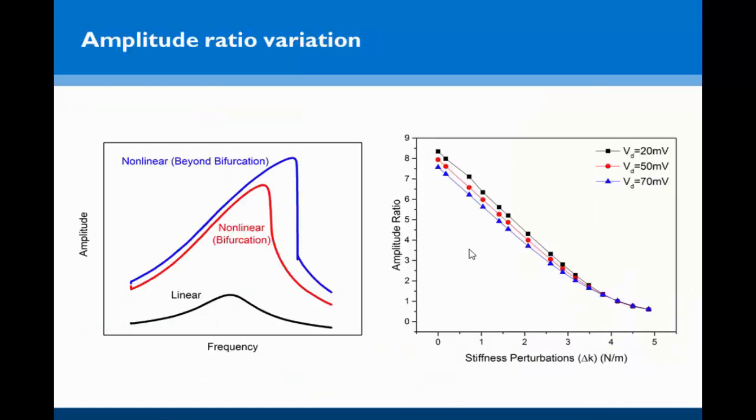If we move on to the results, the way we've designed this experiment is we've worked with three different operating regimes. One of them is in the linear regime, so a small amplitude of vibration. One of them is at nonlinear bifurcation limit, which is generally the limit before instability kicks in, and one beyond bifurcation, where we see the instability already in place.